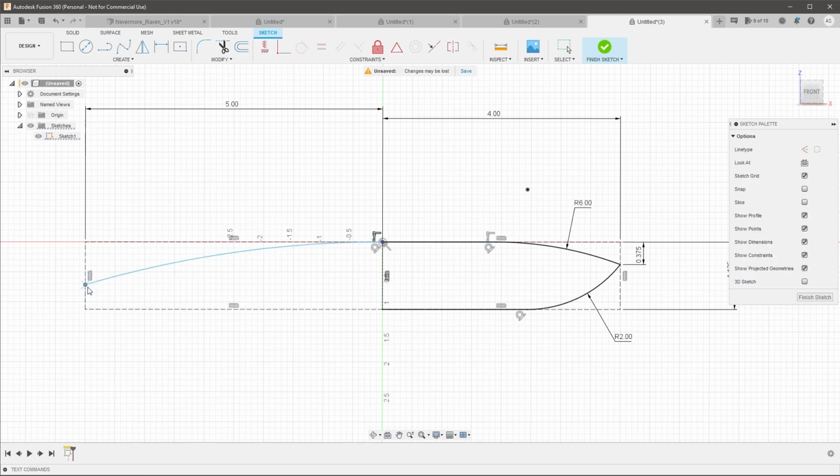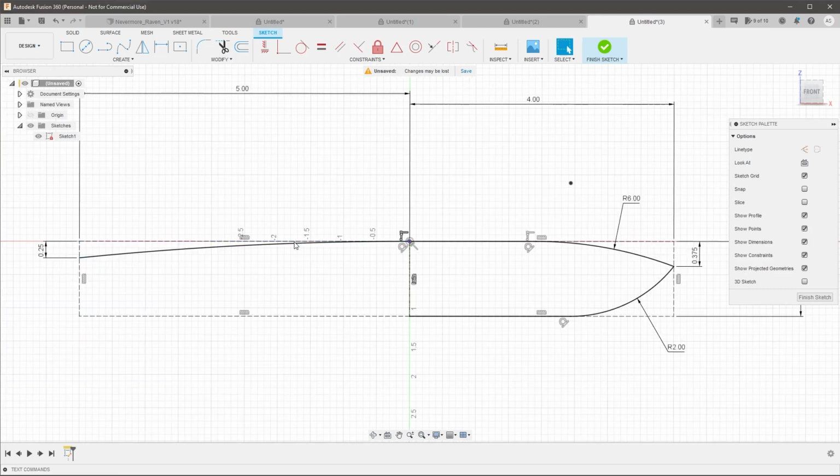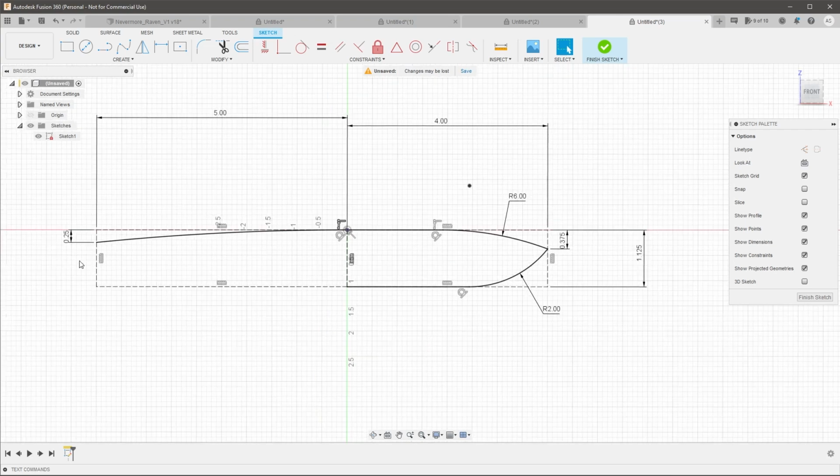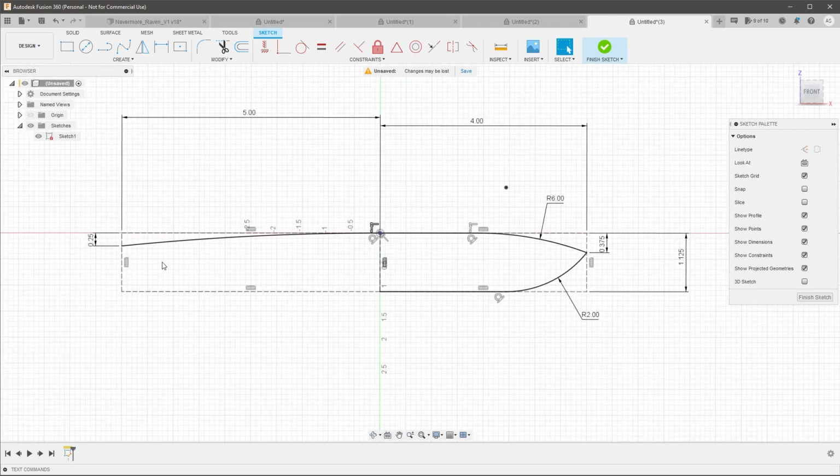And then I'm going to say, where do I want this to fall? Do I want this to fall at the same depth of here? Well, if I wanted it to line up with this one, I could just make those horizontal, and now that is fully constrained. Or maybe I don't want it to go that far down. I can go 0.25 from that top line. So I'm recessing this line by 0.25 inches. I'm going to go ahead and leave that one there.